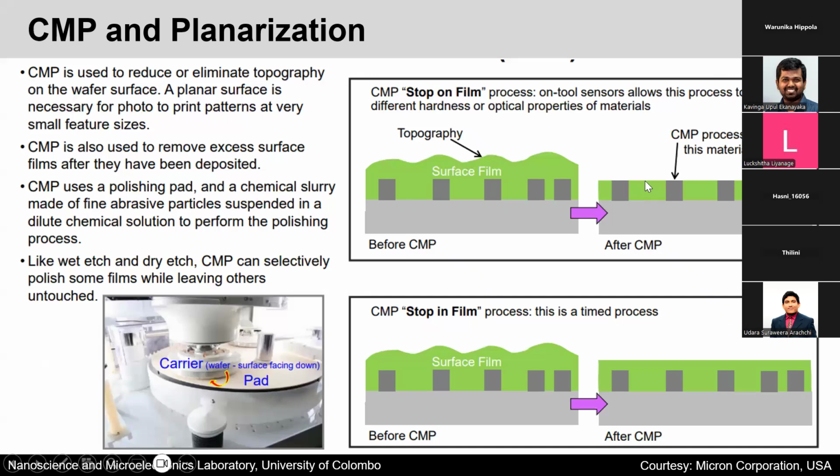So when you reach a particular material, the etch actually stops by itself, right? And then you have made the wafer flat again. That's called planarization. There are multiple CMP methods to achieve flat surfaces, and you can read up about it if you are particularly interested in CMP.